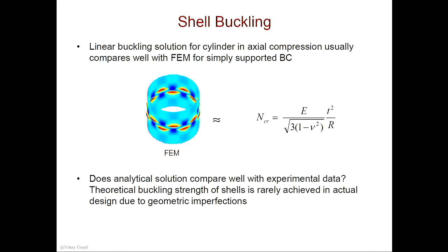And so what happens is that if a structure is built and it has an imperfection, say there's a very small imperfection in the wall, and I now load it up, trust me, that imperfection will become very important. If I took that can that you had and put an imperfection in on purpose and loaded it up again, I'm pretty sure, like if I took a can of Coke and put a dent in there, it would be easier to buckle than if everything was straight and there was no imperfection.